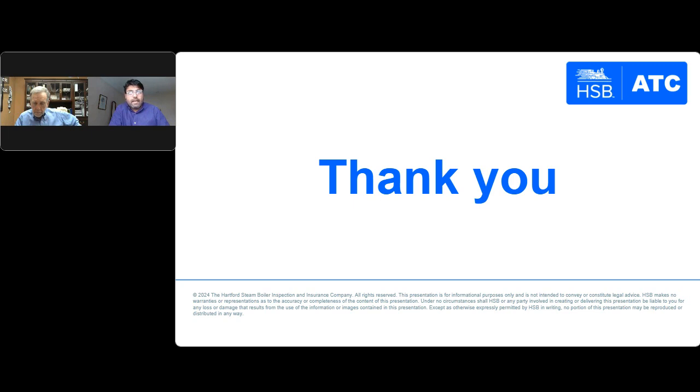That will happen regardless of whether it's an equal T or reducing T. The key thing is whether you have enough thickness around the crotch, where the stresses will be higher than in the rest of the T. So the answer is no. I don't think it really matters in terms of reducing Ts or equal Ts.